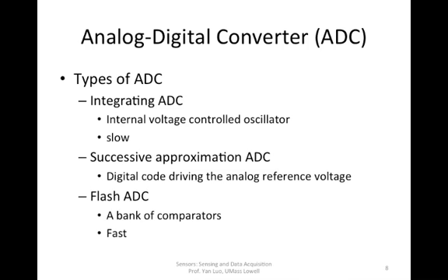As time goes, the input voltage will gradually ramp up, and the reference voltage will be the threshold where you can know by how much time this input voltage causes the output of the integrator to be 0. Using this reference voltage and the oscillator for the time, you can then estimate the input voltage level and convert that to a digital value.